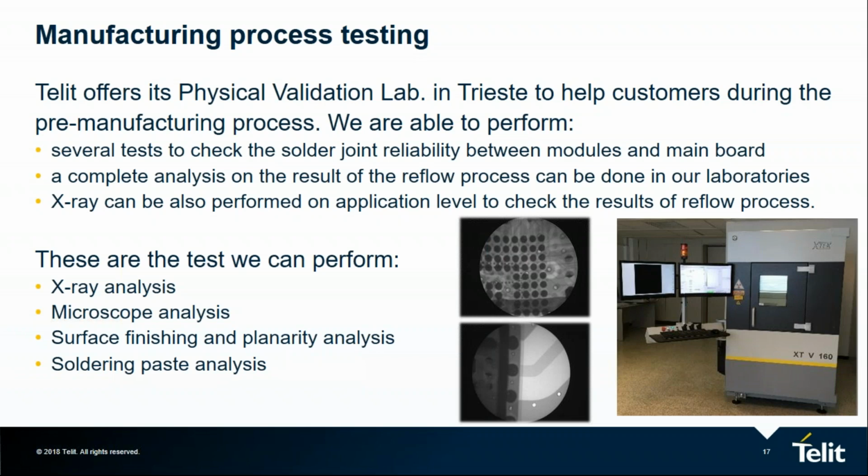the module and the main board, and can be performed in our lab, like X-ray analysis, cross-section of the solder joints in order to verify the quality of the joint, complete analysis of the reflow process used by the customer or his contract manufacturer in case of specific issues that are identified, and other tests like surface finishing, planarity analysis, and also solder paste analysis.